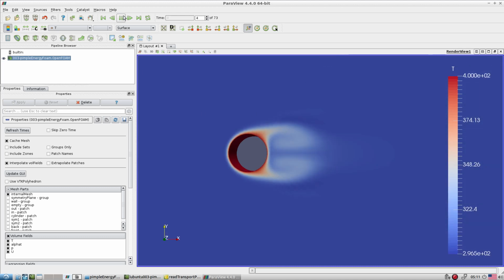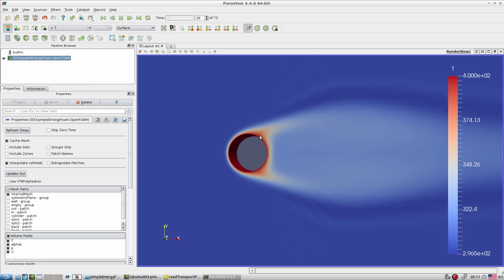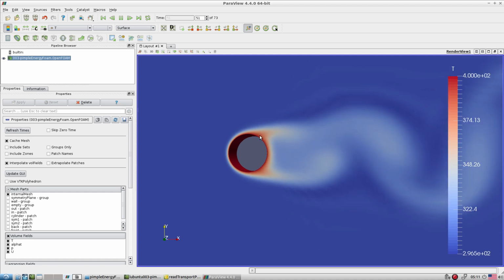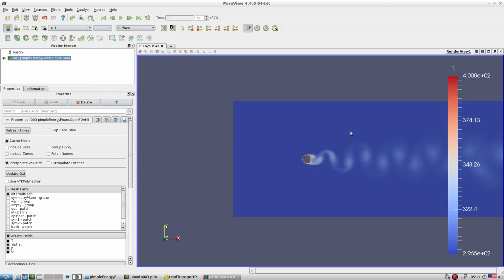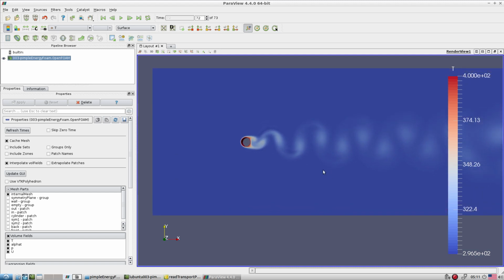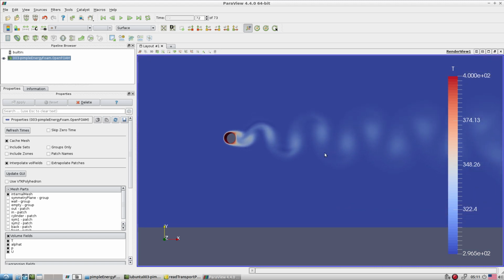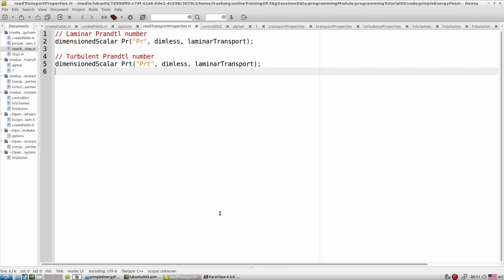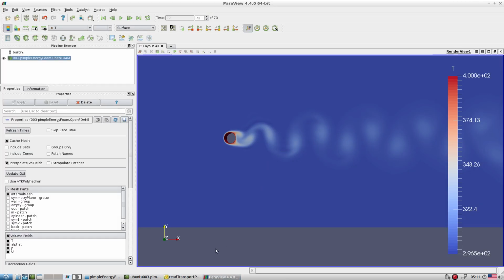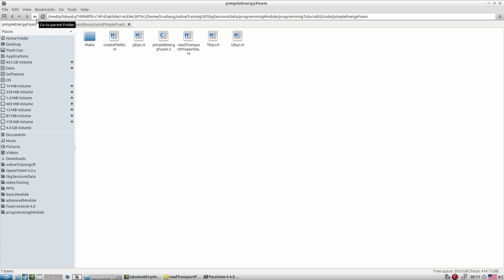Okay, so let's run it from scratch. One can very quickly generate a different class of solver, add the changes inside the OpenFOAM environment, create a new solver, create new test cases and set up the entire environment inside OpenFOAM, so that we can add scalar transport type equations. So I suggest you also try to incorporate these energy equations inside the PIMPLE form by your own way, and also generate this test case and start running this tutorial.